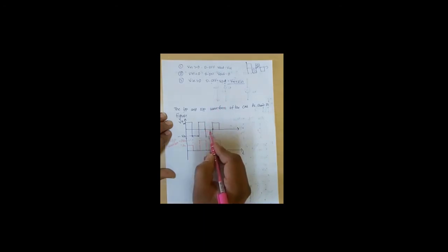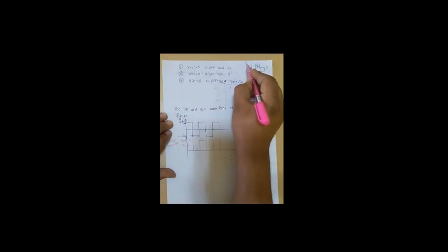In this mathematical equation, for the input voltage V input, we first consider 0. In the initial first positive half cycle, the output voltage equals Vm, therefore here we draw the output voltage equal to Vm. During the negative half cycle, the output voltage is 0, therefore here we get the output voltage equal to 0.